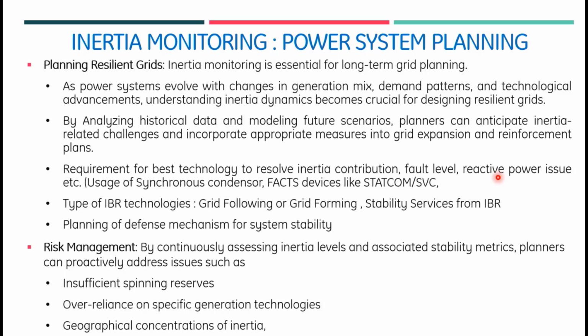It also helps in planning your defense mechanism for the future power system when the inertia is low: how different controllers like the IBR technology and FACTS STATCOMs provide a response to the system in terms of active power for frequency control and reactive power for voltage control. You have to plan your defense mechanism in case there are stability issues. So it basically provides risk management for the system operators.